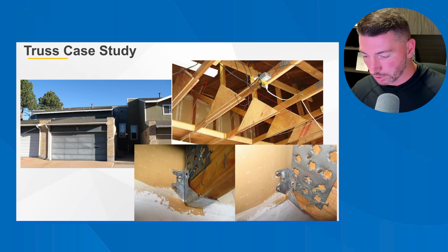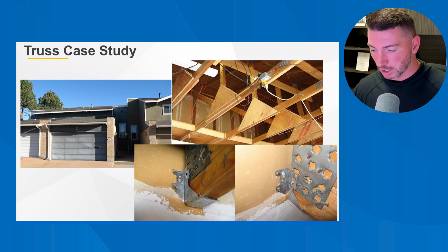Well, looking over the wall, you'll notice that the hangers seem to be small for the load they're carrying, which is very true. The hangers turned out to be sized for a 2x4, which is far too small for the roof load they're carrying. There are fasteners with a total of 4 gold deck screws each. And that is very sketchy.